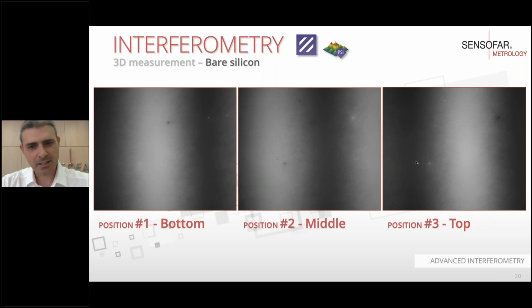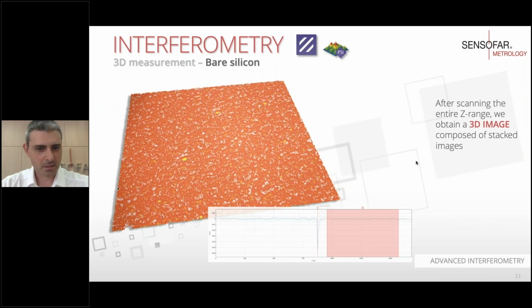That is about 60 nanometer steps, performed by shifting the position of the measuring sensor head against the sample. And this is the result. This is a bare silicon surface with some defects we want to analyze, and those defects are only something like 50 nanometers deep.